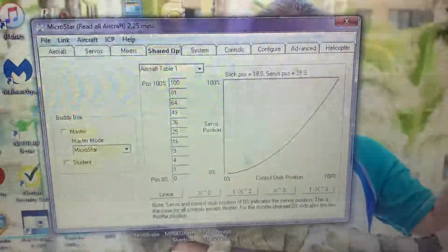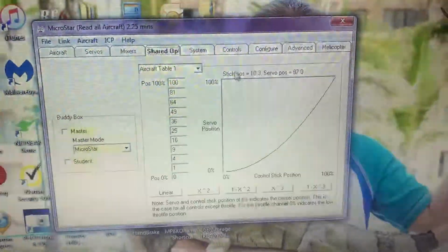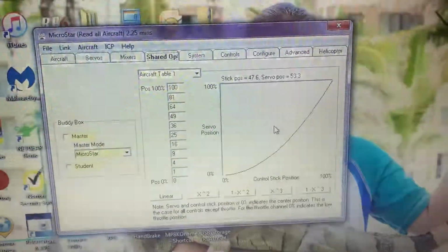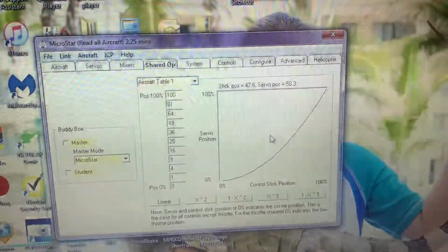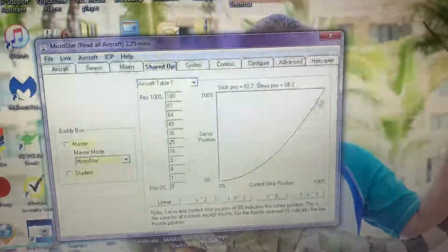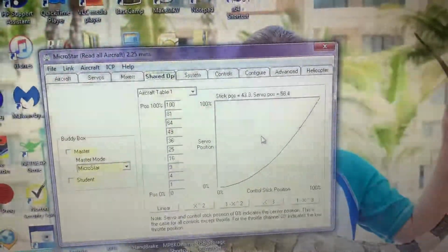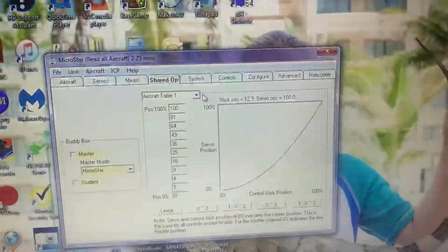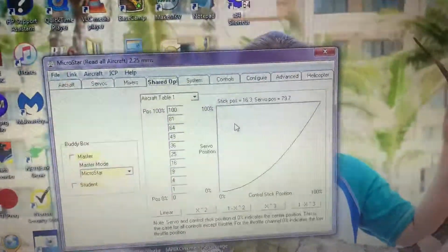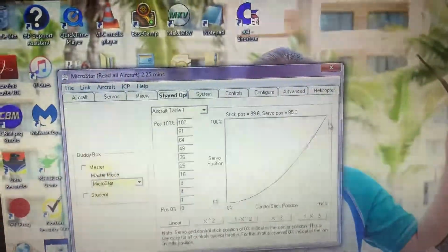You can run an exponential curve, a linear curve. If you have a throttle curve, in a stunt mode you can run a V curve. If you have your collective pitch set so that center stick is 0 degrees collective pitch, you can have your throttle curve where high stick is 100% throttle, mid stick might be 80%, and then low stick might be back to 100% because you're pulling negative collective pitch. And then vice versa, you could set this curve up for your pitch curve.